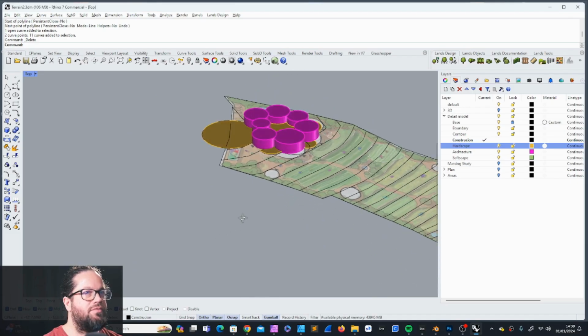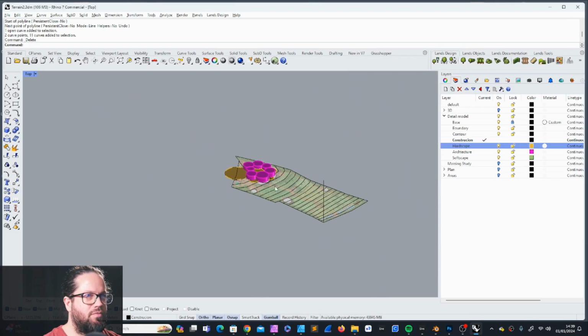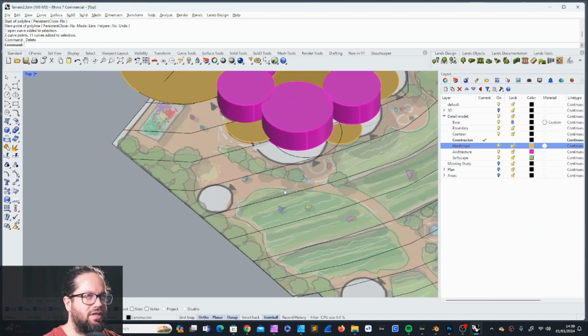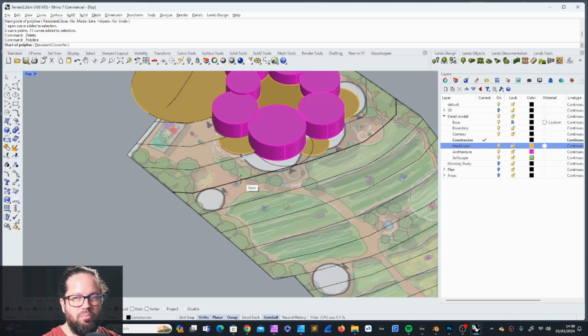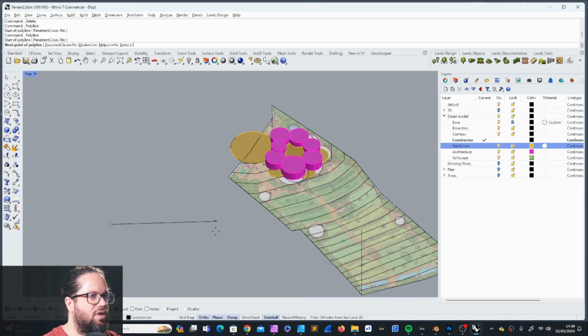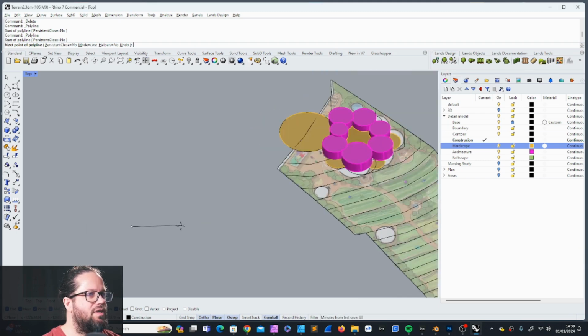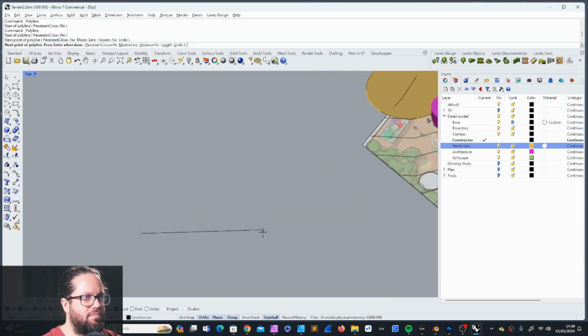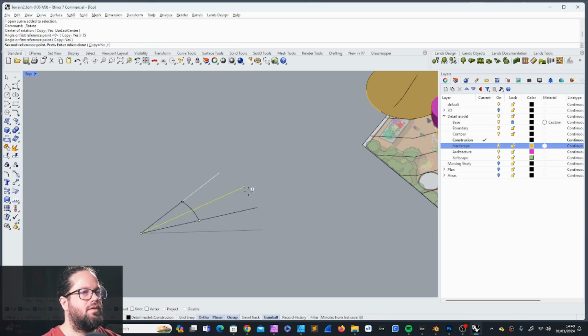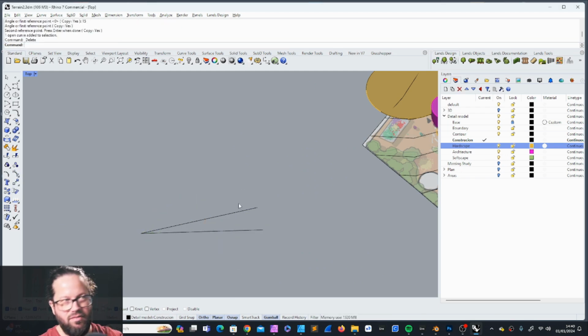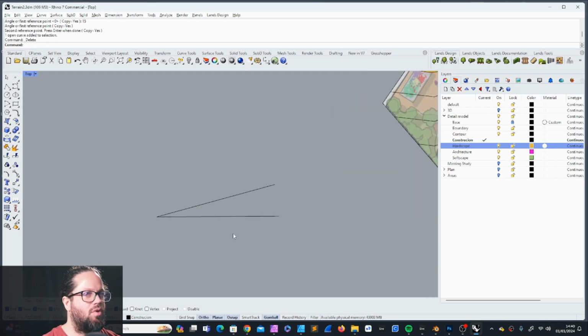All right, in terms of steepness of the slope, we want to get to a slope which is still walkable. We can define the paths with just lines, but based on a principle. It says you can still walk a slope which is 15%, sorry, 15 degrees. 15 degrees is a lot. If I'm measuring this, let's see, I will rotate this by 15 degrees. It says 15 to 20 degrees. Now, 20 degrees, you can still walk, but it's going to be hard.